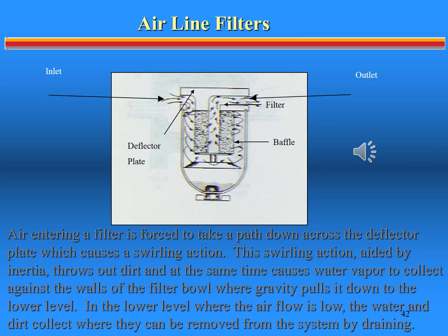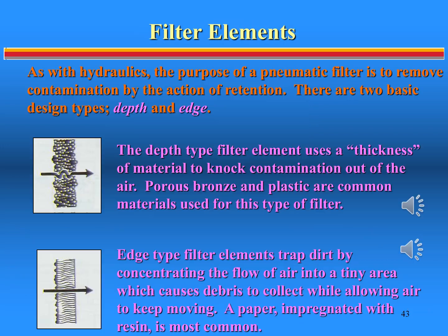The operation of the airline filter is like any other filter, with the addition of a set of fins which cause air to spin at high velocity. At high velocity, the water molecules collect upon the sides of the bezel and fall into the bottom where they can be drained. This component should be inspected daily.